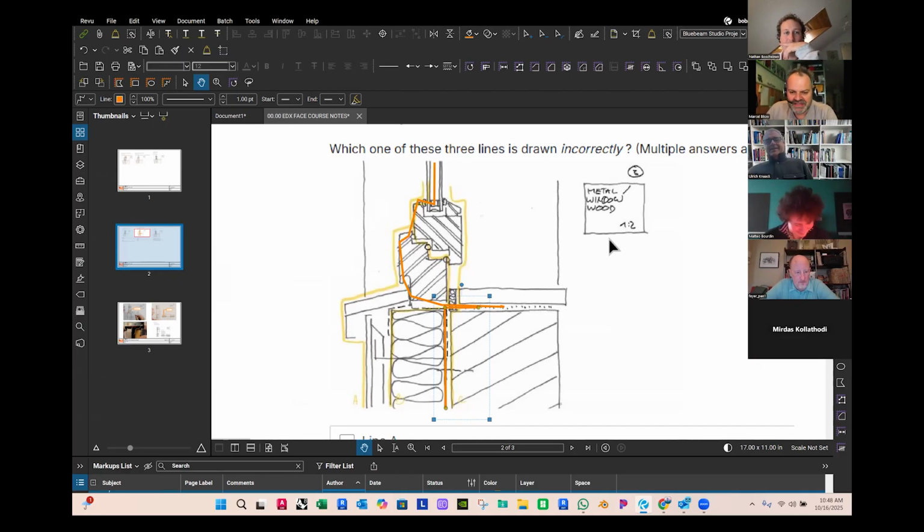So sorry for that. But in your case, the orange line, we assume that the window profile, this might be out of wood, that the wood itself is already, let's say, water or vapor tight. So therefore, the watertight or the vapor tight, airtight layer is on the inside and not on the outside. So in order to make things a little bit simpler, we would say the outside is when the rain hits, you want to make sure that it is all tight and sealed. That's what you already understand, and that's also right. That's why we also have it running down the sill and drops over with the overhangs.